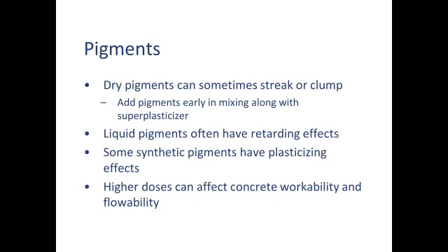And of course, anytime you add a lot of a pigment, you're adding a lot of a fine particle that has a lot of surface area, so you're going to be changing the workability of your concrete. This is most prevalent with carbon black, which is very, very small particles. High doses of carbon black can really affect the workability, making it difficult to make it flowable or pourable.